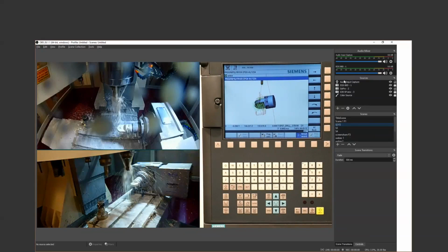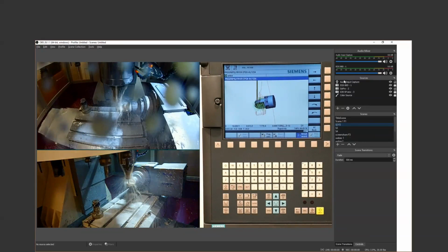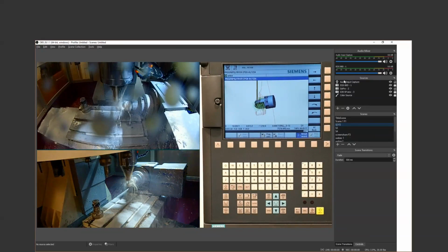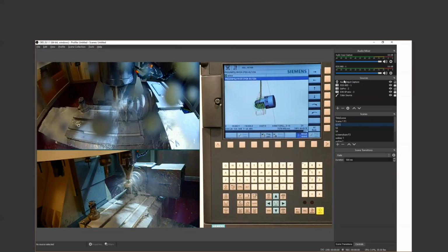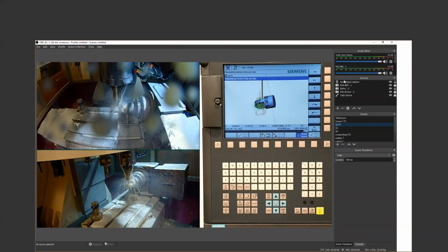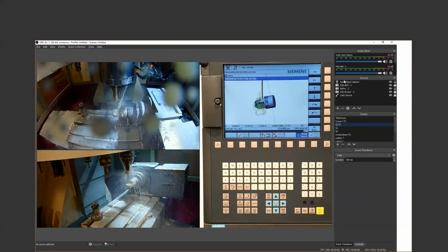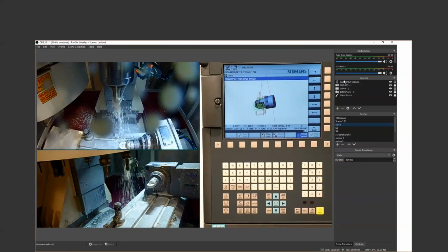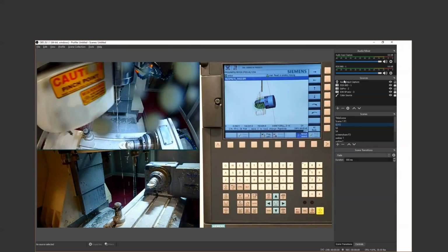Now we're going to put the right size drill in the right hole. That's always a good thing. You know what I like too? I liked how it was smart enough to stop the spindle before it did that retract, so it can let the spindle decelerate right there, you see, so I can get into chip and out of chip as quick as